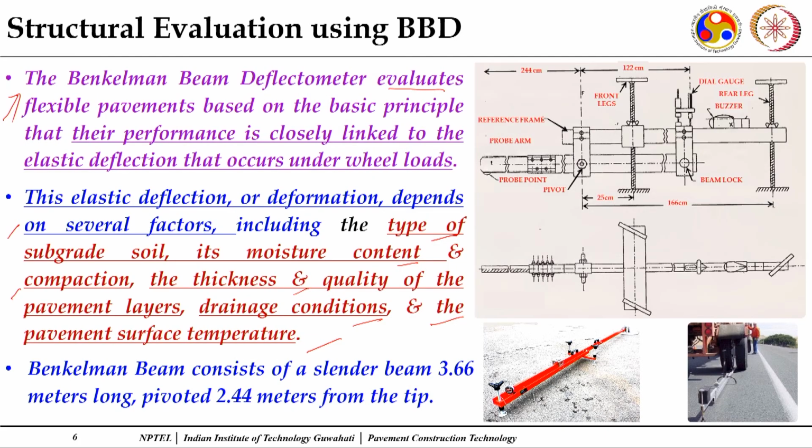If there is a good thickness of bituminous courses, then that also plays a role. So, the deflection under a load used in this Benkelman beam deflection technique will try to capture this information about the pavement structure as a whole.